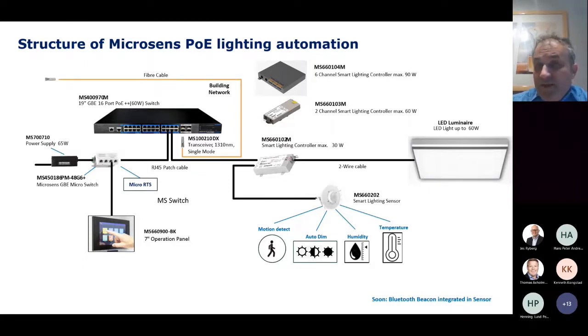And so you can connect your lighting system next to your phone as a second system directly into your network. So another important advantage of those systems is that because everything is based on this PoE standard and on this networking hardware component, there's no need to do this job by an electrician, which is an obligation if you run systems by 230 volts.